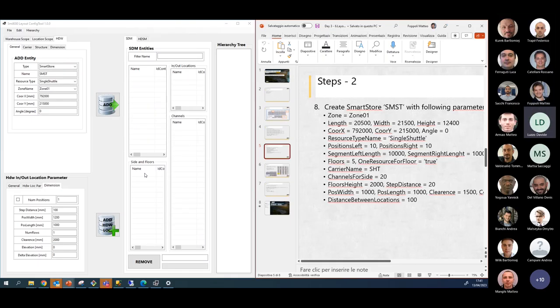Sometimes it should work also to launch: when you launch, go in property and disable DPI settings, because it's the same problem that we have with the GUI, the legacy GUI. Okay. I didn't know it. So I will check also this thing. Maybe it's a setting that should be set by default, something like this. I don't know. But okay. Thanks for the suggestion.